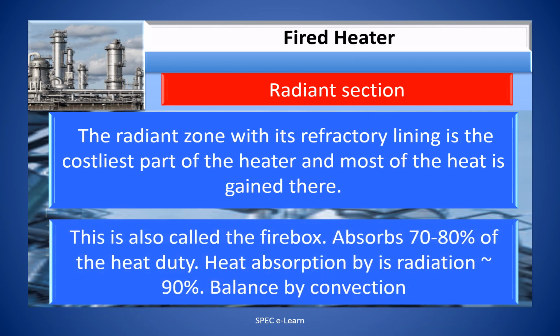This is also called the firebox. It absorbs 70 to 80% of the total heat duty of the fired heater. Heat absorption by radiation is approximately 90%. The balance is by convection.